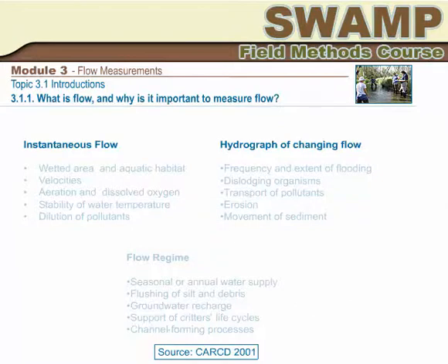For a single storm, or a span of time such as individual years or seasons, or as statistical averages of many storms, years, or seasons. Flow regime refers to patterns in a stream's hydrographs, whether natural or the result of human activities. Characteristics of flow regimes that might be important for stream assessment include annual peaks or lows, duration of peaks or lows, and average time between recurrences of a particular size storm.